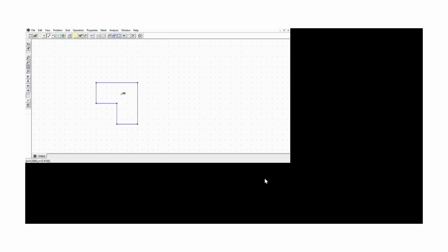As per your electrostatic problem to be solved in FEMM, first I have to create small elements. I have to break down this model into small elements. Once it is saved, I have to click this yellow color button so that it will create the mesh, or number of elements. As I've just given my mesh size to be 0.025, it will happen with respect to each element of size 0.025 for this total model. If not, the default triangular mesh will be formed.